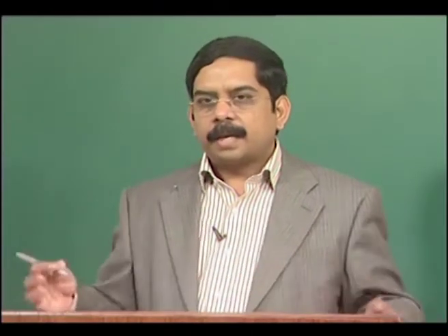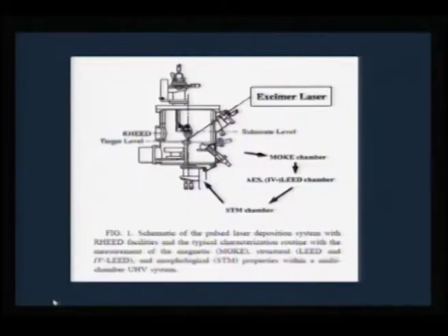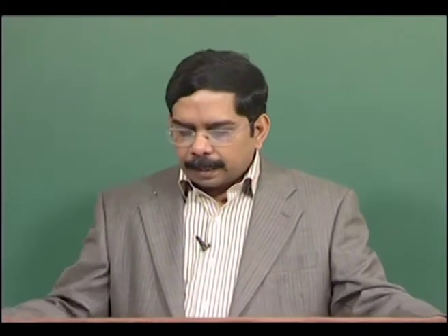So epitaxy is the underlying word. Therefore, certainly this is different from MBE. As I told you in the last lecture, an MBE chamber is usually tagged to other characterization techniques like RHEED, magneto-optical Kerr effect, low energy electron spectroscopy, and also to an STM. But a PLD instrument is not necessarily interfaced with all these other techniques, in the sense you have the luxury of breaking the vacuum and taking the material out for characterization.